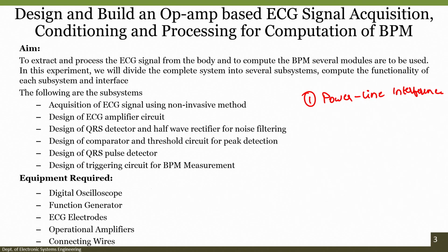Generally in India the operating frequency is somewhere around 50 Hz. So, when we see the raw ECG signal and compute it in the frequency domain, we can see there will be a peak at every odd multiple of the frequency of our power line. That is nothing but at 50, 150 as well as 300 Hz. That signal is not required. So, that means at 50, 150 as well as 300 Hz and beyond, we may not require all these frequencies.